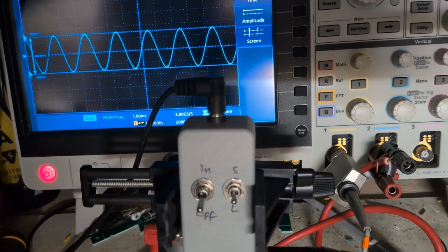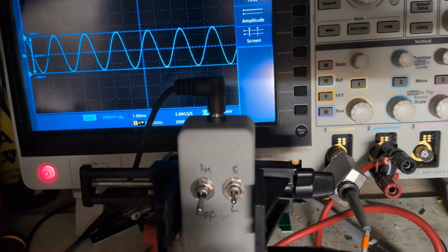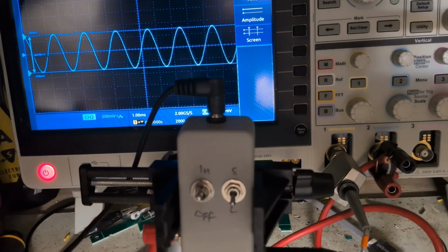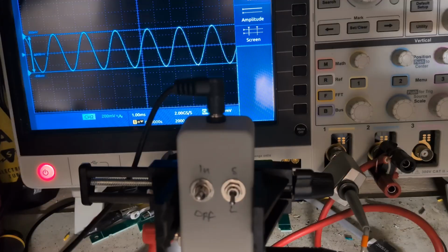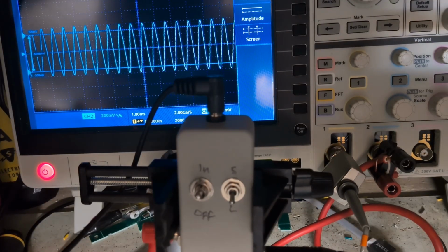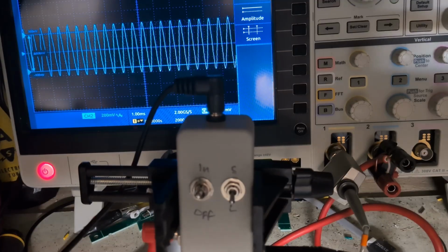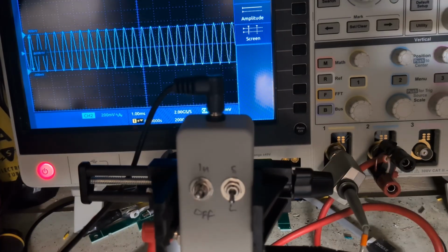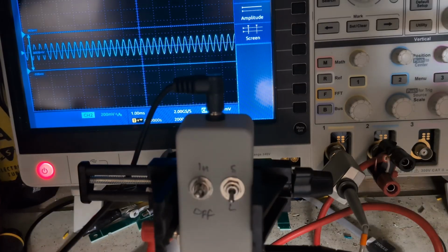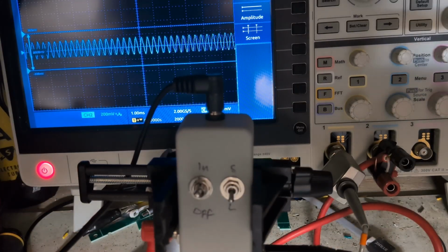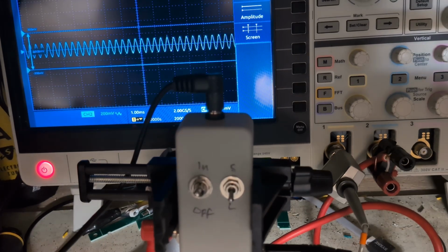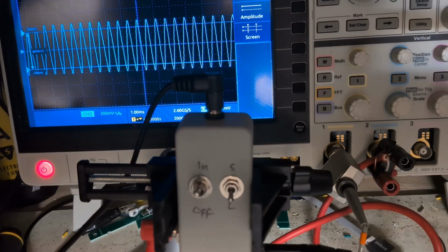Now I'm going to engage the inductive part. Okay, so low frequency, no change. And then we're going to increase the frequency, 100 hertz at a time. You can see now we've exceeded the lines. And then the signal's going down again, and it's going down quite a lot. So that frequency is about 2.6 kilohertz. And then let's try and find that peak again. I'm going down in frequency.